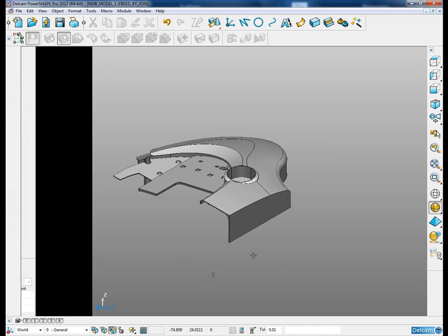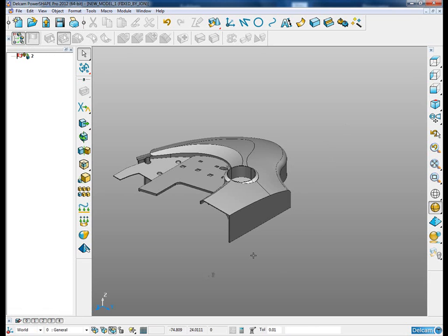So once we've finished the basic modelling operations, we'll take a look in our solid history tree, and we can see that we are still working with a completely dumb solid. If we remember, we brought this solid in as an XT file, so it could have come from any PowerSolid based modelling system. So we have no history. Now there are various features that we can see in this model, and there are various reasons why you would want a feature-based history tree.